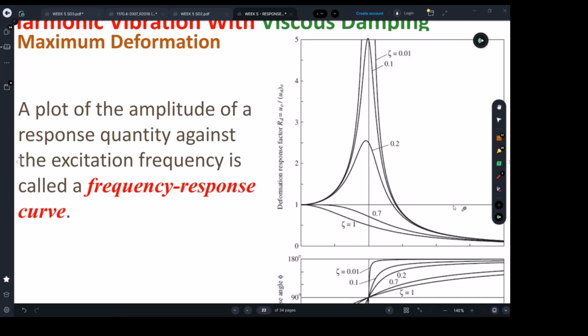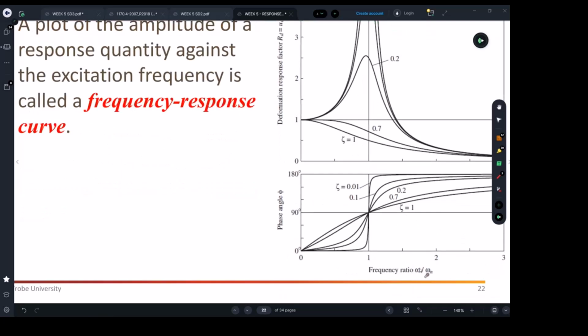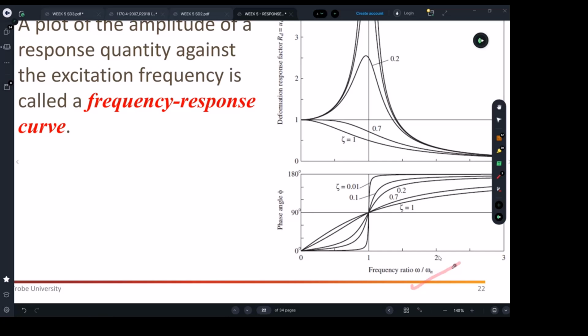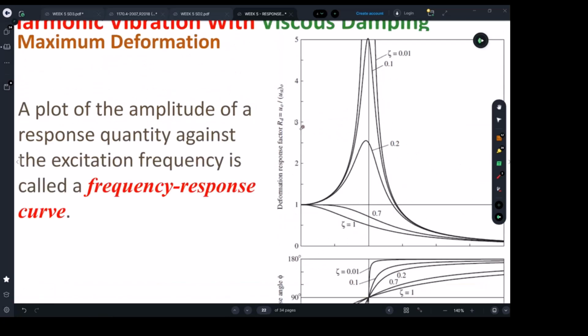Because by the time you know the forcing frequency and you are able to calculate the natural frequency of the building, you should be okay with this ratio. Then it depends whether you want to find the dynamic response. You can use this curve in a reversed way, or maybe you want to see where it sits here and find how critical it is. All right.